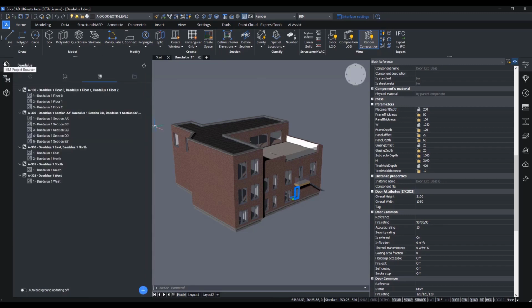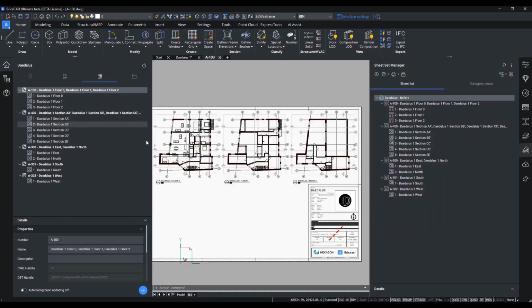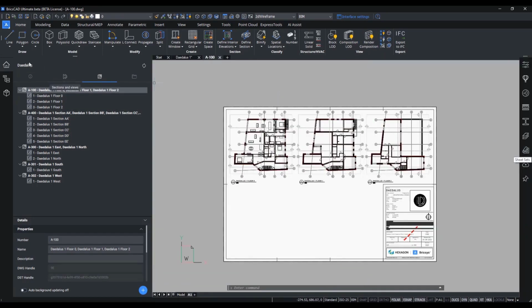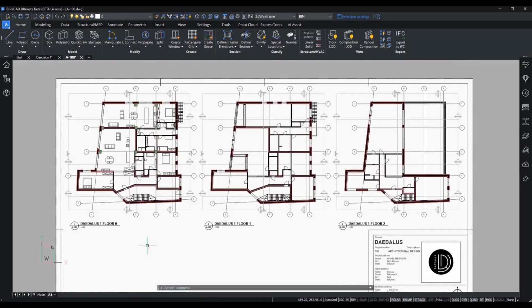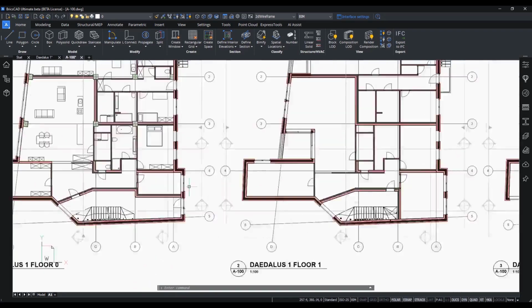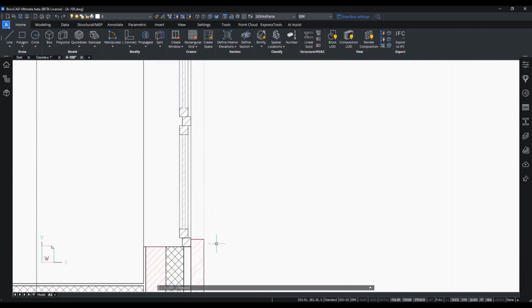When making a new project, your default documentation set will look something like this. The default look is defined by the BricsCAD BIM templates in the template folder and in the support folder. I won't go in depth about customizing these templates, as in V23 we can overrule these default templates in a type plan instead, where we can specifically filter out the elements based on their BIM data and customize the generated lines per filtering. Now, in this default representation, we see that the windows are represented by their actual cut objects, and we would like to change this to symbols instead.